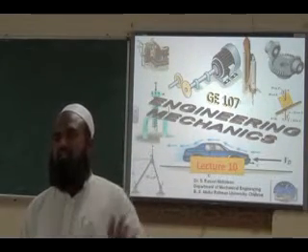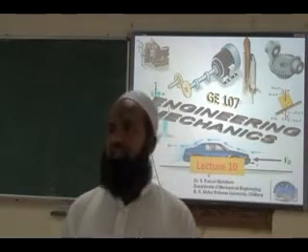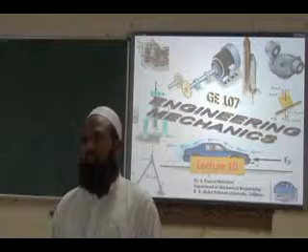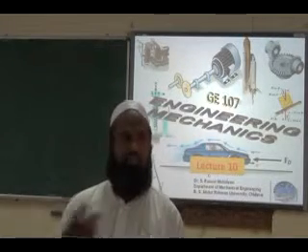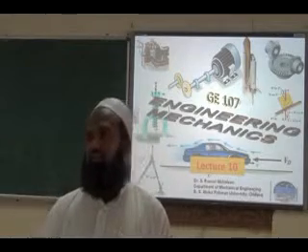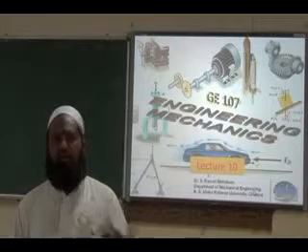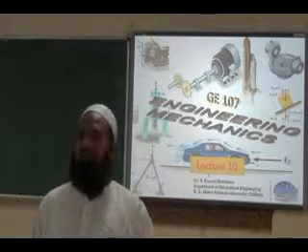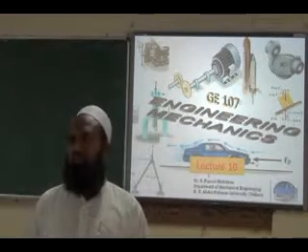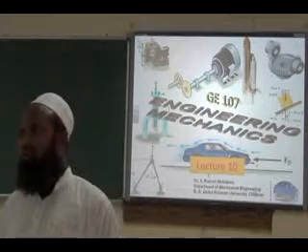Generally there are 6 degrees of freedom your body can have in space. So you will have 6 reactions, 3 forces and 3 moments. You can translate along X, Y and Z, and you can rotate about X, Y and Z. So along X, Y, Z you will have forces, and about X, Y, Z you will have moments. So they may be supporting forces, reactive forces, or reactive moments.